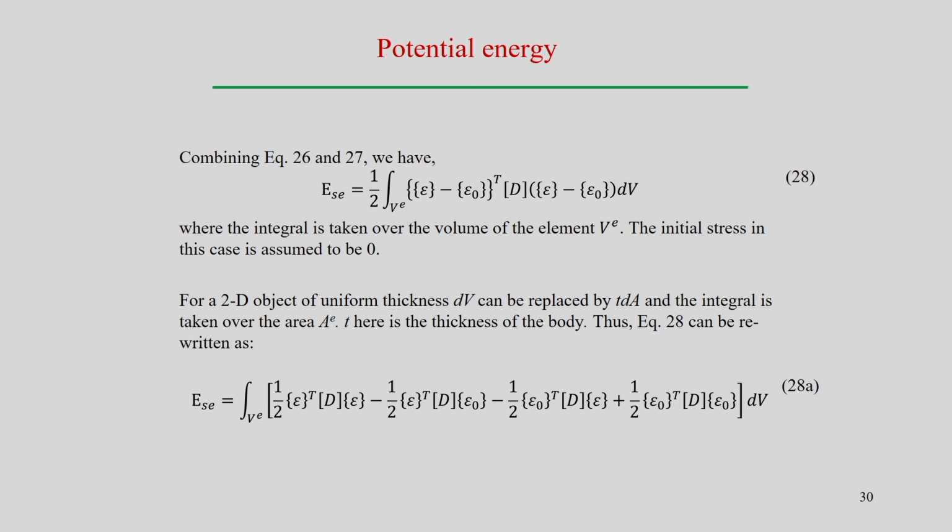Now, once we look into all these things, the D matrix, this energy can be represented like that. This is the strain component, and this is also a strain component, because this corresponds to the stress value, and this corresponds to the strain value. So, we simply use the D matrix to relate between the stress and strain, and depending upon the situation different forms of the D matrix are possible. Now, this is the strain component and this is the stress component into dV,